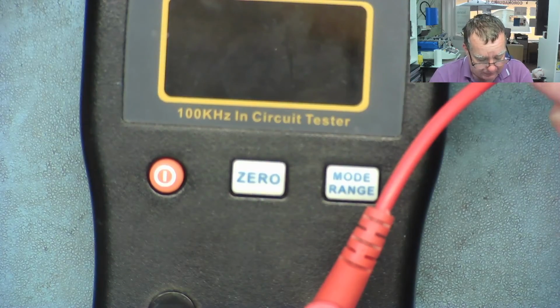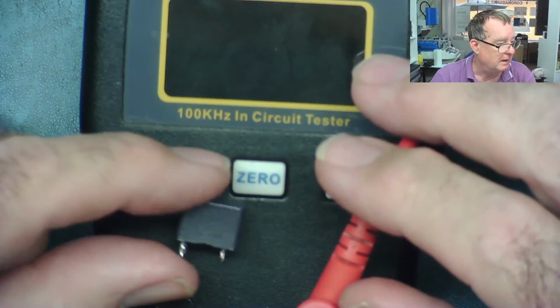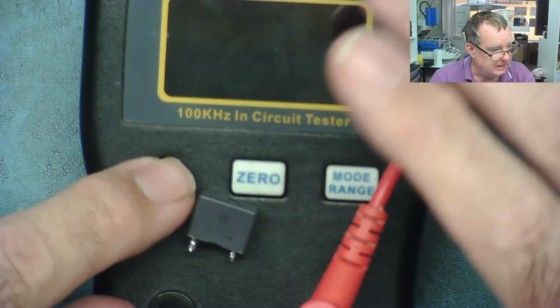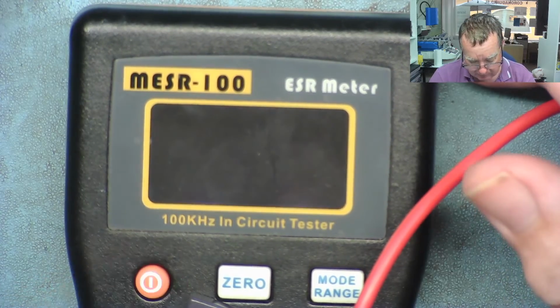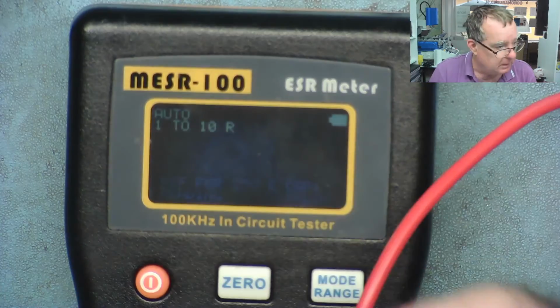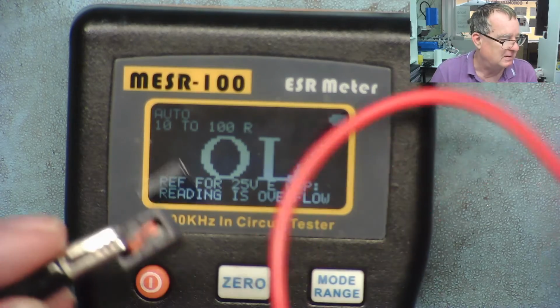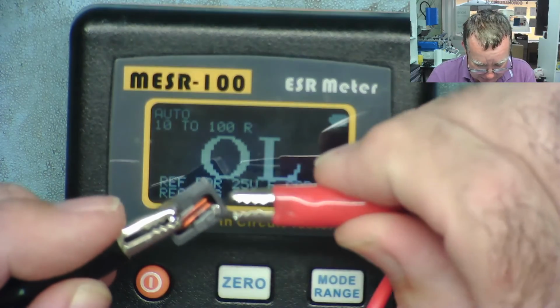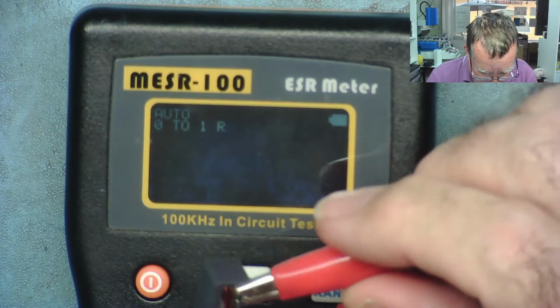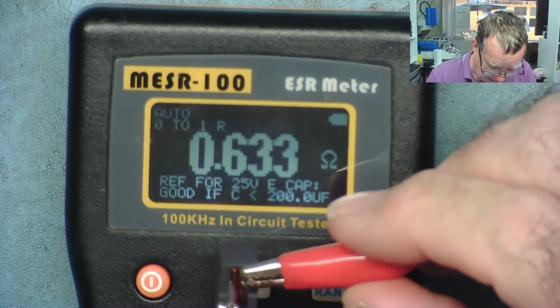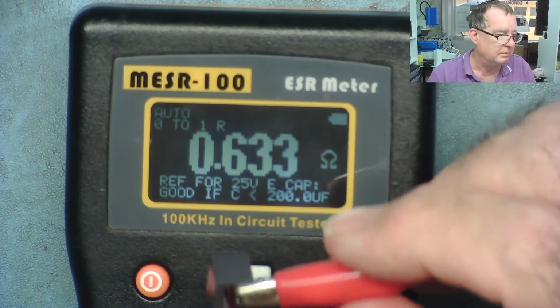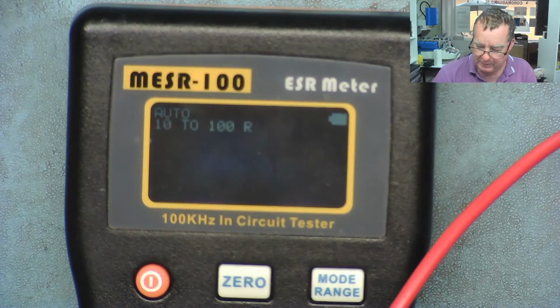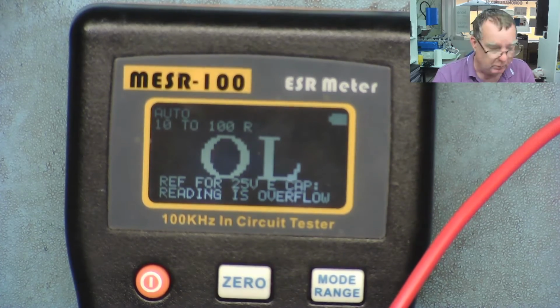So there is a way we can actually measure them. We'll have a look first. So this is the 1 microhenry inductor, and we'll put it on the ESR meter. This is the ESR meter, okay? We'll switch the ESR meter on, and let's have a look to see what this tells us. Normally this is used to test equivalent series resistance in capacitors, which it tells us in ohms. So this is actually going to measure this in ohms. Okay, good connection. That's reading 0.631. Okay, 0.631. So I'll just make a note of that one. 0.631 ohms, yeah?